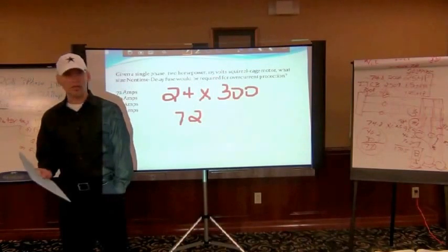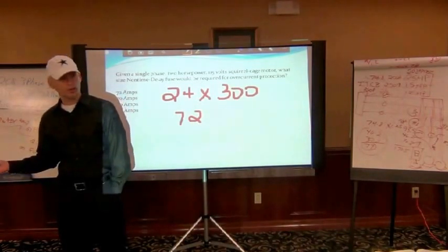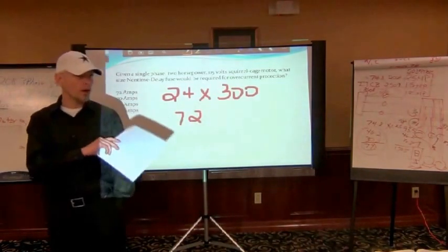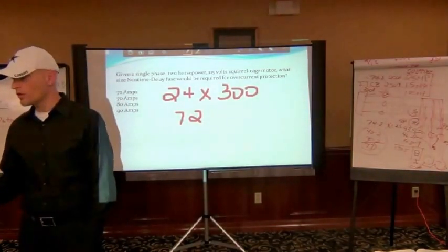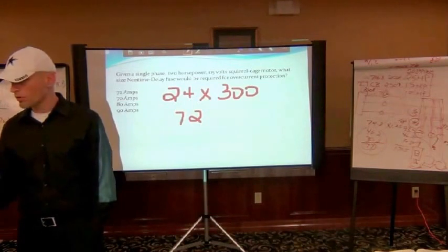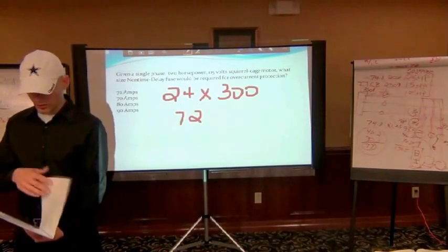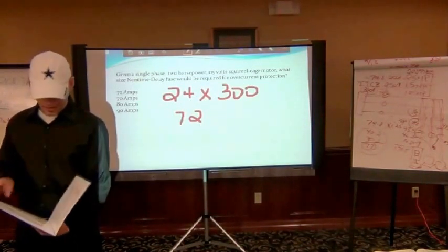So an intermittent duty doesn't have anything to do with inverse time circuit breaker sizing, but it does have something to do with wire size. Vice versa, short time duty rating doesn't have anything to do with heaters, right? So make sure that you're not trying to put service factors and ambient temperature on wire size either.